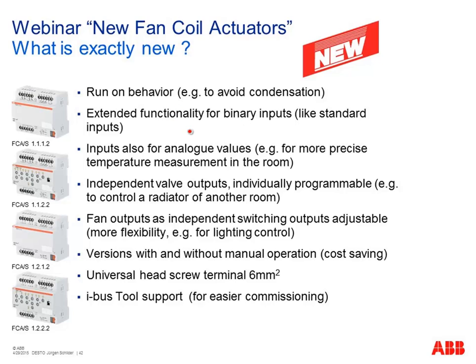The binary inputs have extended functionality, like the standard inputs you normally expect, so it also gives you more options. You can use inputs also for analog measurement, temperature measurement with PT100, PT1000, so for more precise temperature measurement in the room, independent of the room temperature controller.